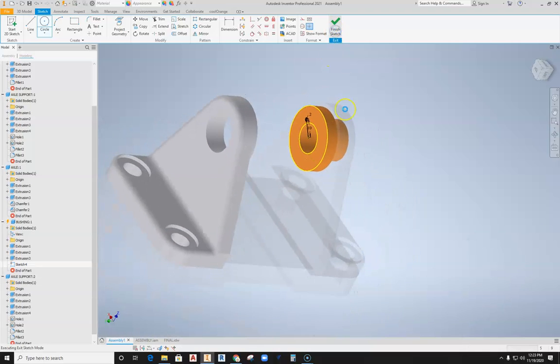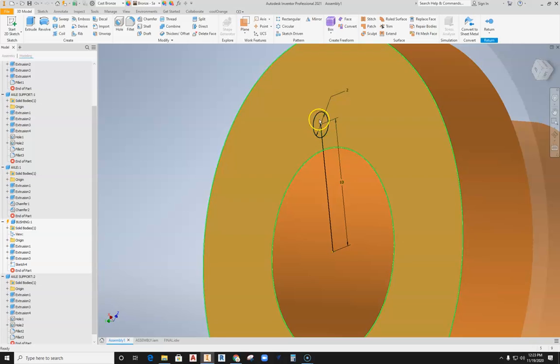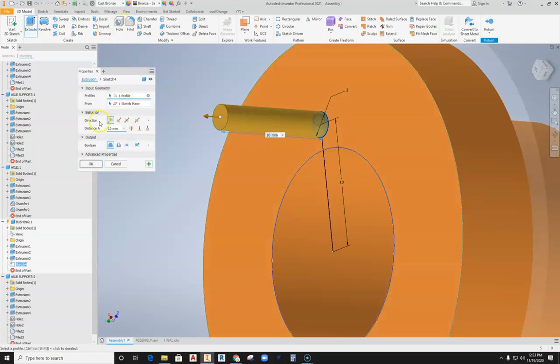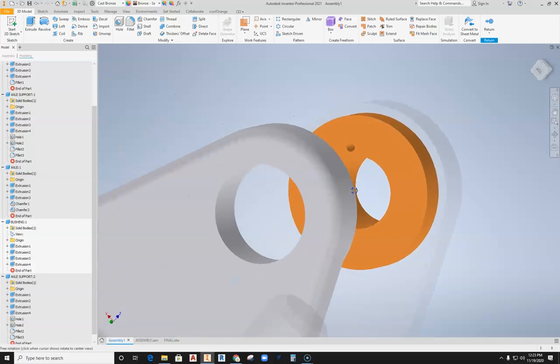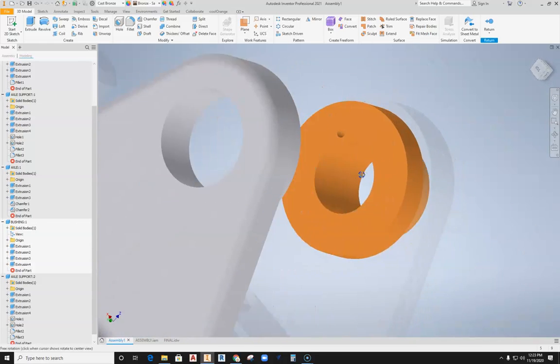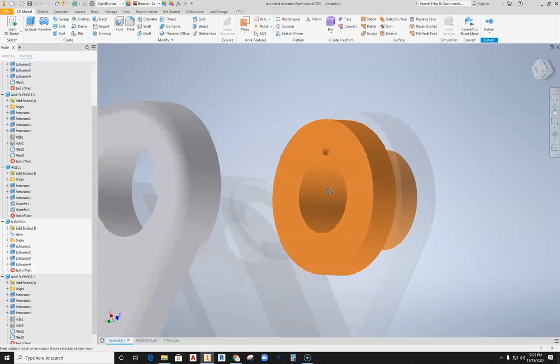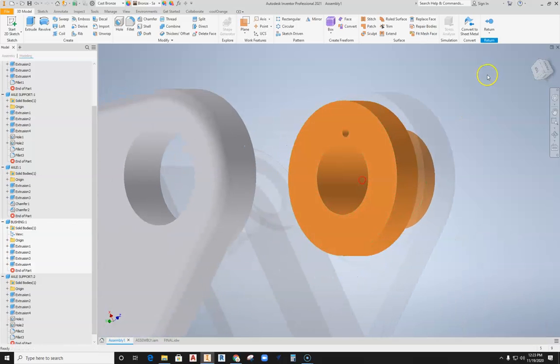Then I will finish the sketch. All I'm doing is putting something here and drilling a hole through it. So I'm going to grab my extrude tool and do a negative extrusion through the bushing, so that I'm placing a hole into the bushing. There's no meaning or reason other than I want a hole in my bushing so that I can see the bushing turning as I move it.